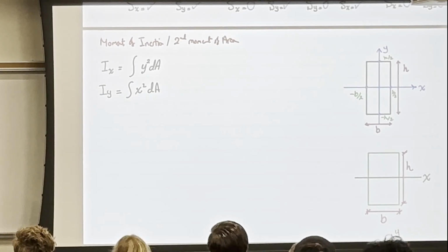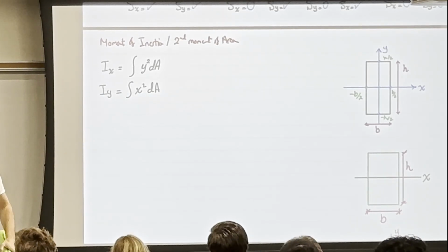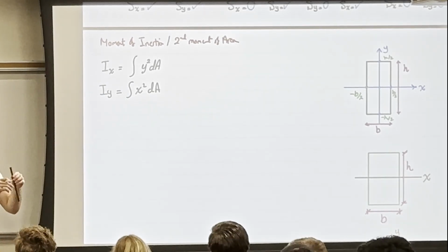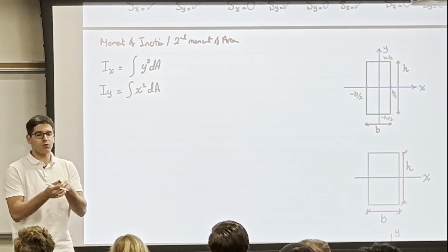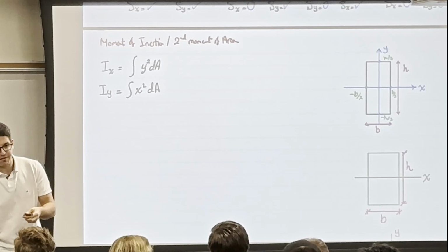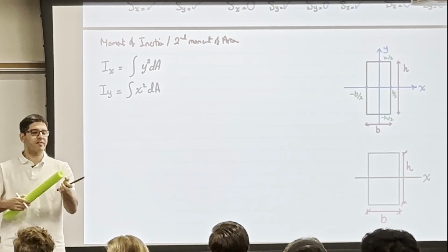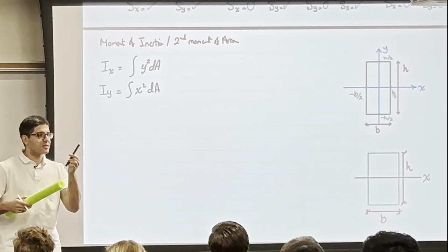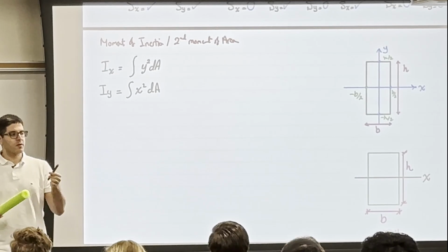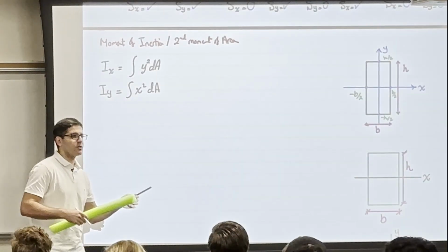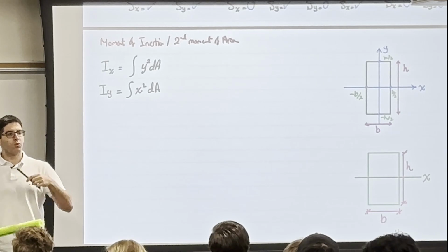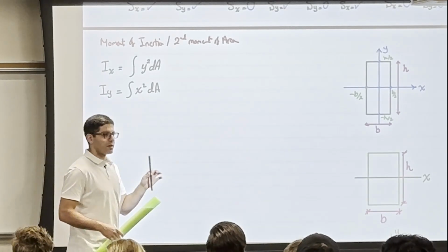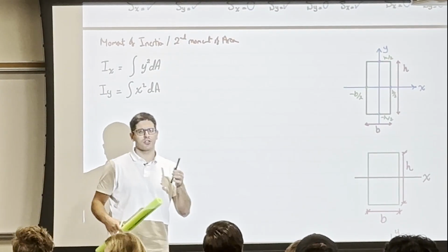And it makes sense, if I have this steel bar, it's made out of steel. There is a stiffness due to the material because it's steel. If I have this material and that material, and they have the same shape, of course the steel is going to be stronger or stiffer. So we have something we call stiffness due to the material, which is symbolized by the elastic modulus, which is E.